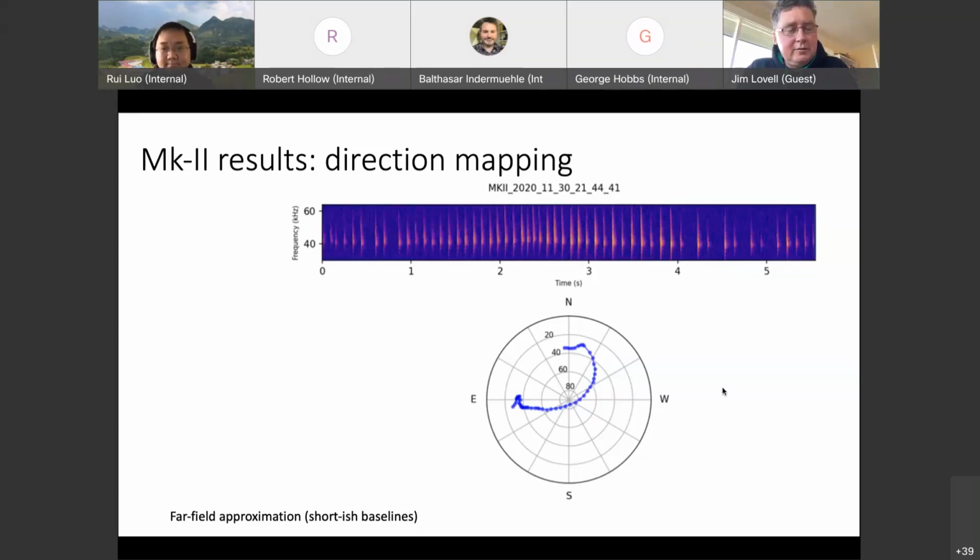And the other question was to do, I'm sorry, I've forgotten. Temperature gradients in the atmosphere. Yeah, the speed of sound changes with temperature, and that is an issue. I haven't really worried too much about that. It's probably at the 1% level, and I'm not quite there with that yet. But it's quite easy to add a temperature sensor to the device and record temperature, and then you can calibrate that out. And in fact, you can do pressure too, because I think pressure is also an issue.